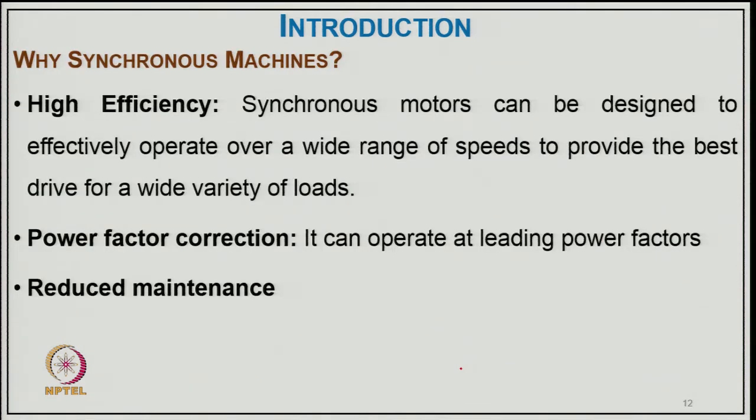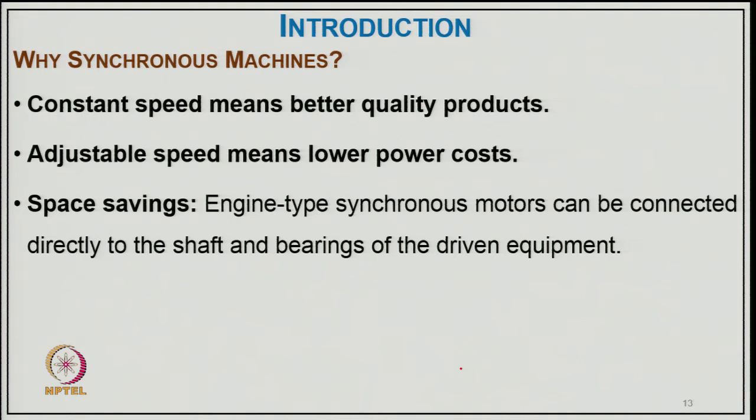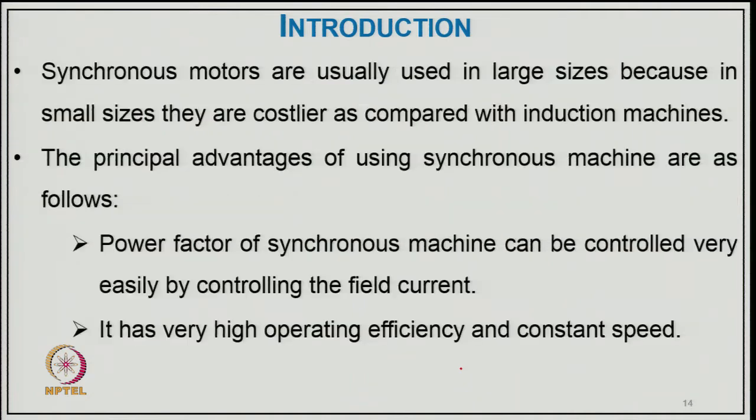So, why synchronous machine? It gives you high efficiency. A synchronous motor can be designed to operate actively over a wide range of speed to provide the best drive for a wide variety of loads, and of course it can provide power factor correction, it can operate at leading power factor, and it requires reduced maintenance. It gives constant speed, meaning better quality product, and adjustable speed, meaning lower power cost, and it gives space savings. So, engine type synchronous motors can be connected directly to the shaft and bearing of the driven equipment. Synchronous motors are usually used in large sizes because in small sizes they are costlier compared to the induction machine.